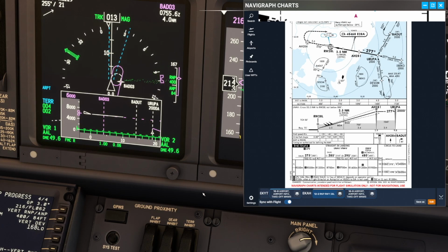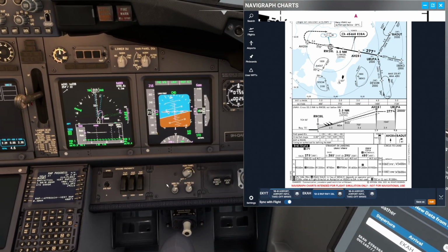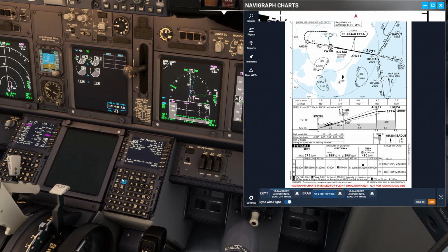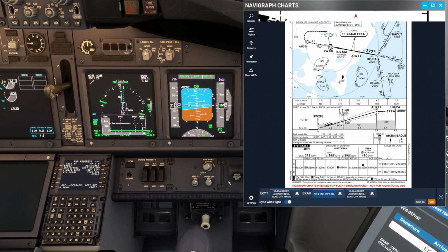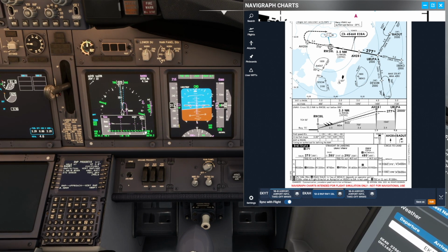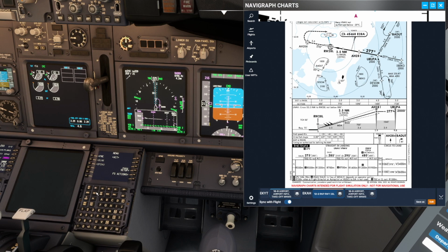So now we talked about QNH blunder error and how we mitigate it. So we expect at roughly 7 miles the RA call of 2500, and we expect on the VSD to see the terrain above, exactly on the terrain actually. Good. So let's go back here for the setup of our approach.